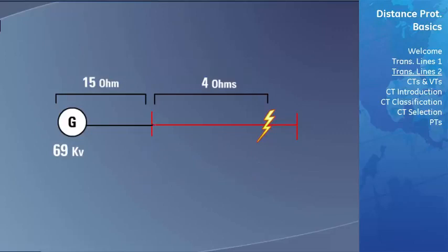As you can see, the system impedance ratio is a very important factor in the stability of a power system at the time of a fault, and must be considered when determining the type of protection needed and the speed that the faults need to be cleared by relaying.